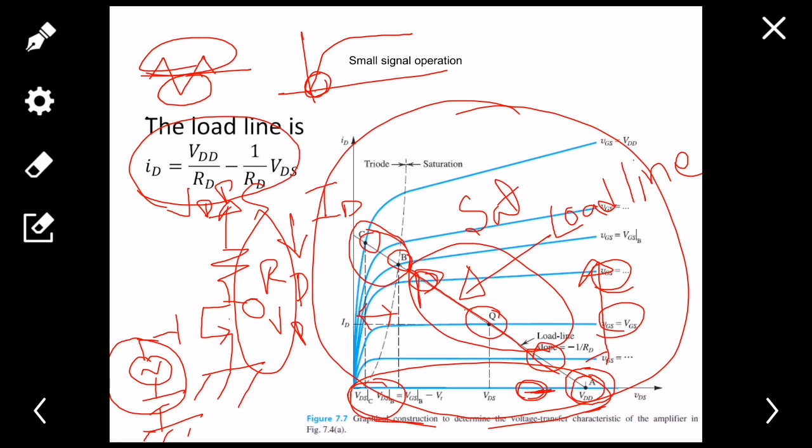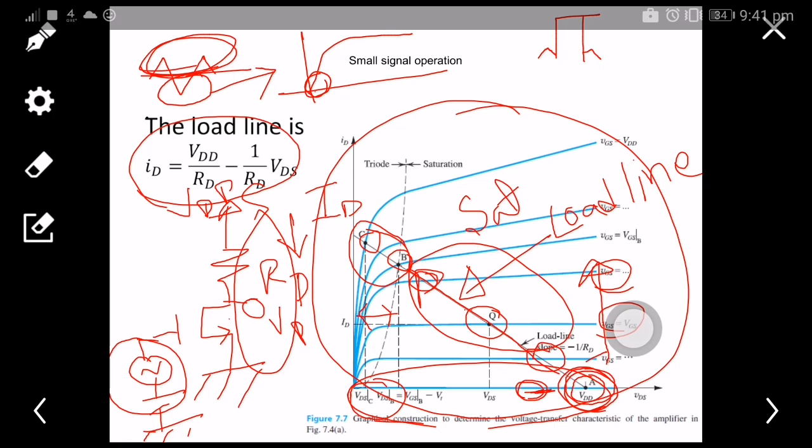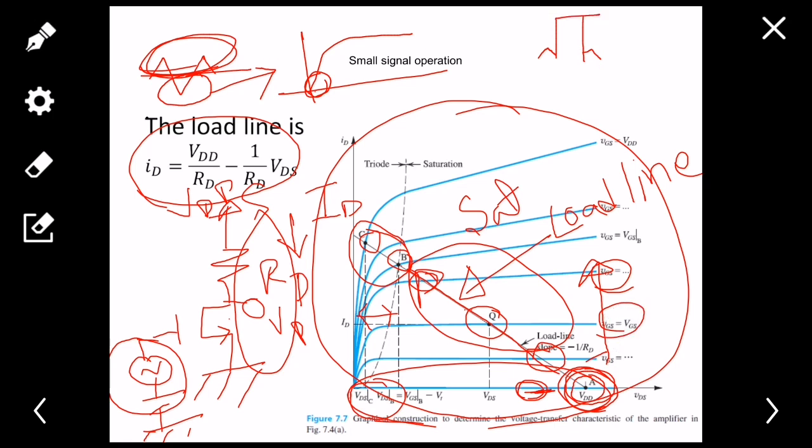So at a negative gate voltage, the NMOS is turned off, and I know turned off means the output is VDD, constant VDD. You won't be getting the amplified signal here. Maybe you'll get an attenuated version of this, but what would the output be? Something like this, huge. So instead of getting amplification, you're getting some attenuation at some portions and turn off at other portions. Basically, the input signal is totally distorted.